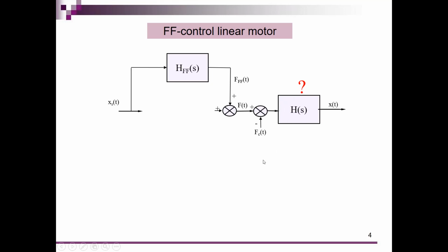So how do we do that? First of all, we start with deriving the differential equation of our system. And when this is only a mass which has to be accelerated in order to get a position over here, then we could draw a free body diagram of this system, and we could say that all the forces acting on that body over here equal m times a, so m times the double derivative of the output signal x over here.